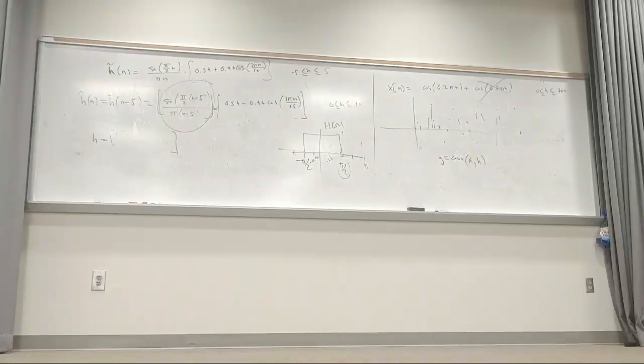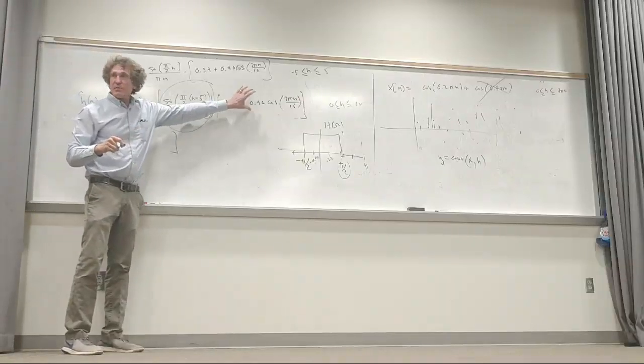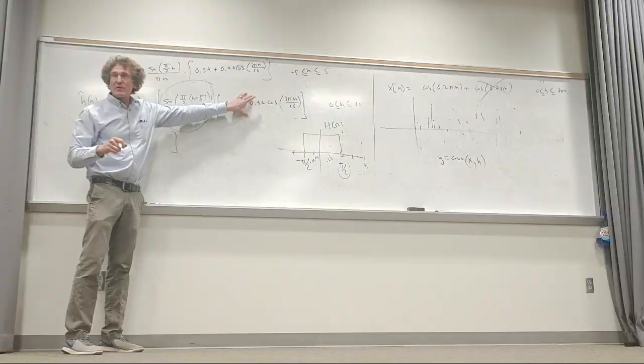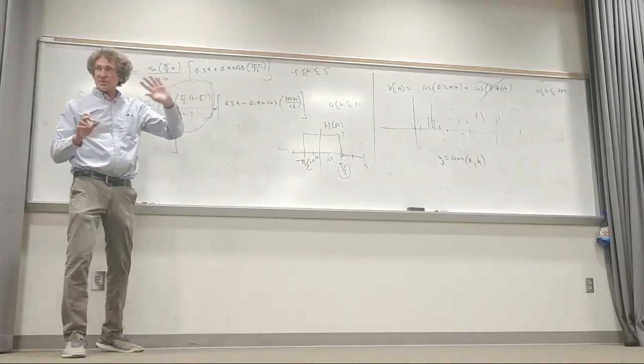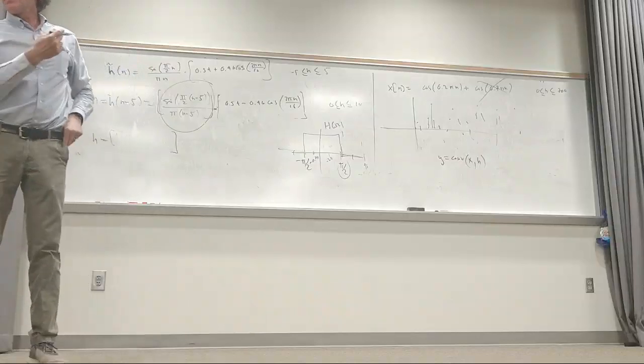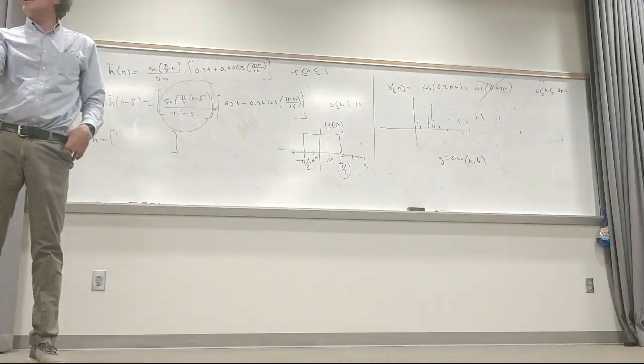We see the sampled signal at the bottom of the page with both waveforms, the cosine of 0.2 pi n, plus the cosine of 0.7 pi n. And then he shows you, after doing the convolution down there, how the filter got rid of the unwanted one. Follow me? Now I want to tell you something. The filtering technique that we used was effective because we did this windowing thing. If you don't do that window, you won't get those results. You'll see the second waveform still fairly apparent. But that window, did anybody do this, by the way? Try that. Does he have the CONV code in there or not?